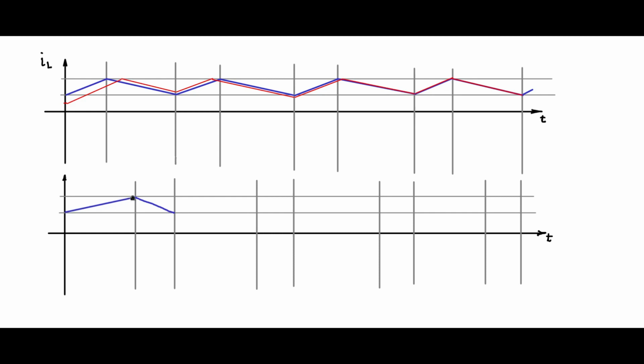So this will be V in minus VB by L. This will be minus VB by L, negative slope, positive slope, negative slope, positive slope, negative slope, so on. So this is the normal expected steady state value of the inductor current under duty cycle greater than 0.5 also. Now here also, like here, we will introduce a disturbance. The disturbance has occurred due to whatever the reason.